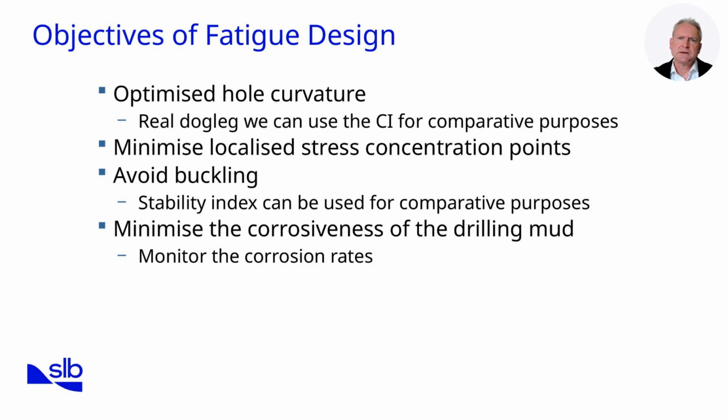Another key objective is avoiding buckling. Even small degrees of buckling, once combined with rotation, can impose damaging cyclic loads. By carefully matching weight on bit, stabilizer placement, and hole angle, we reduce the likelihood of instability. Stability itself can be quantified using indices, which provide comparative guidance when designing drill strings for different well profiles.